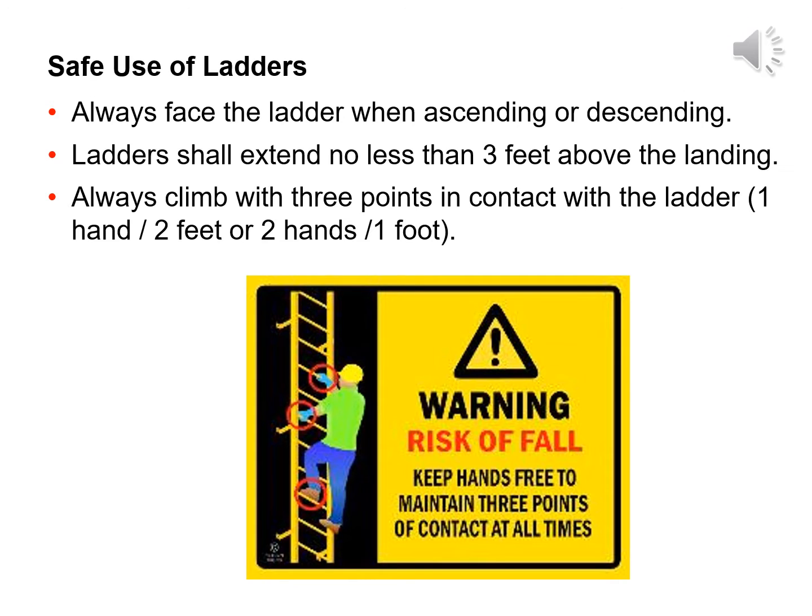It is important to note that the climber must not carry any objects in either hand that can interfere with a firm grip on the ladder. Otherwise, 3 points of contact with the ladder cannot be adequately maintained and the chance of falling is increased in the event a hand or foot slip occurs. Factors contributing to falls from ladders include haste, sudden movement, lack of attention, the condition of the ladder, the user's age or physical condition, or both, and the user's footwear.